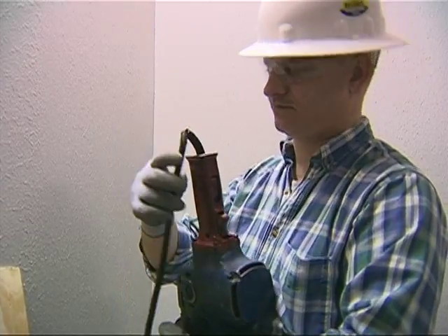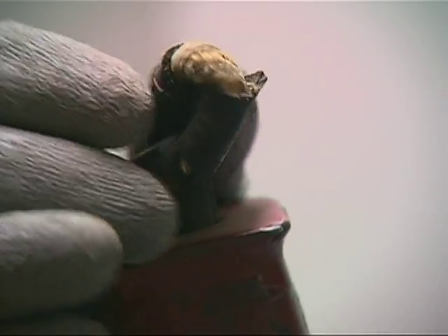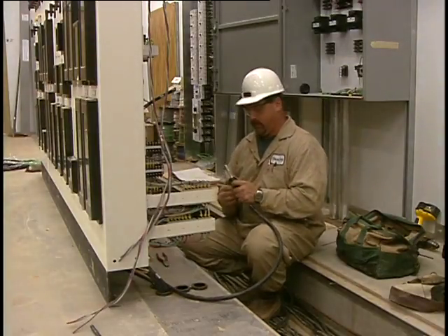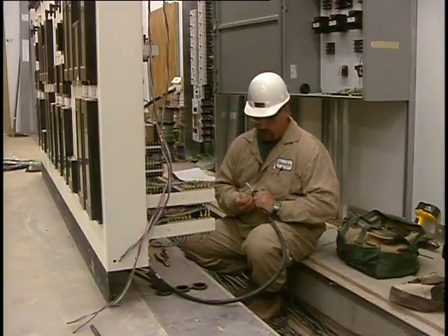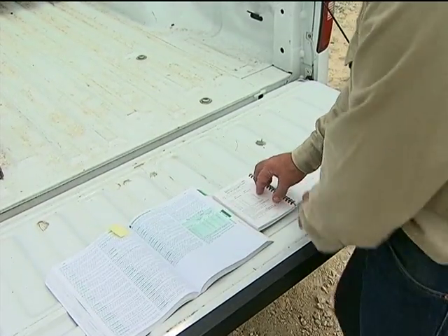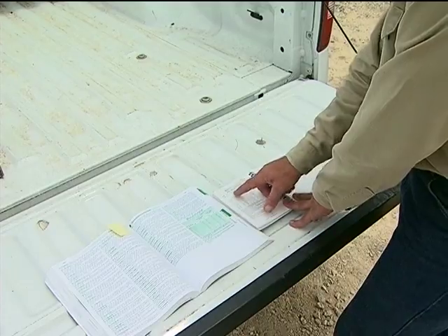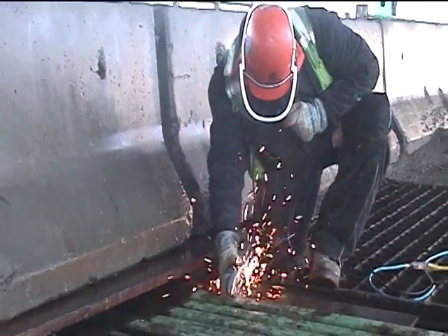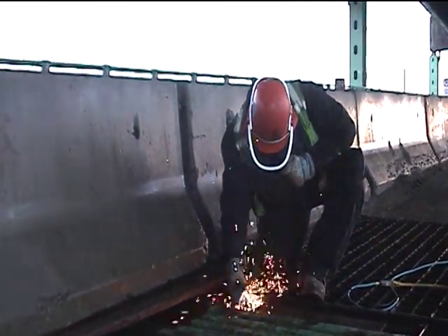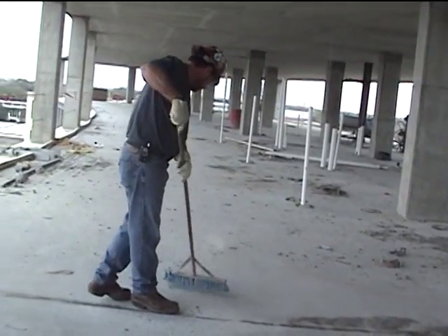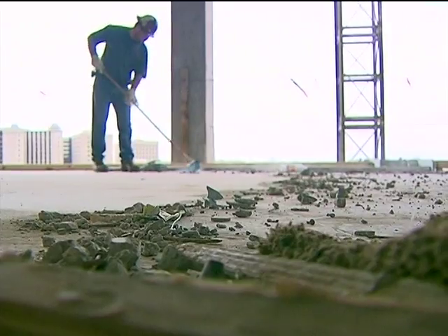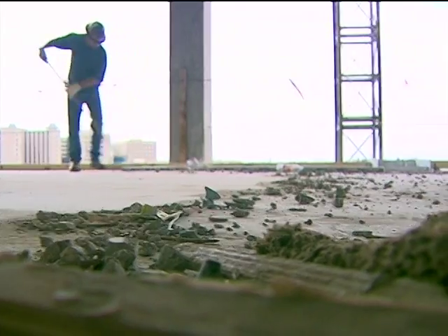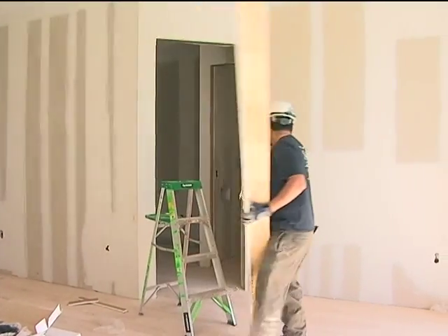Fourth, never attempt to repair damaged tools yourself. Only the manufacturer or an approved repair shop should be used for repairs. Fifth, use tools according to the manufacturer's guidelines. Always read the instruction guide before first use. Sixth, use appropriate personal protective equipment at all times. And finally, keep floors and work areas clean and dry to prevent slips, trips, and falls, and other accidents. Always keep your own work area clean and organized.